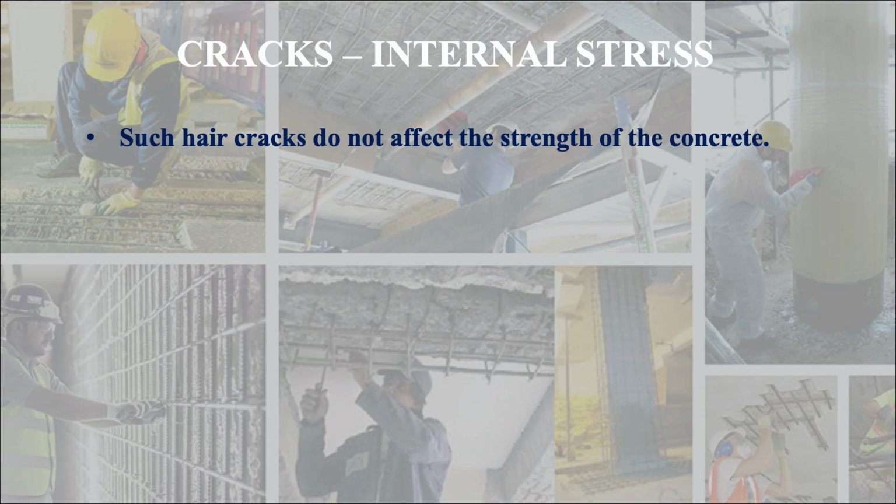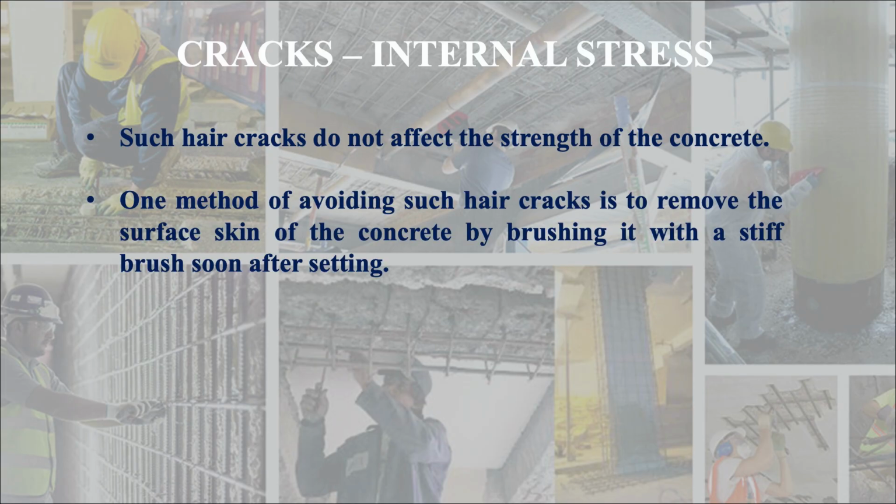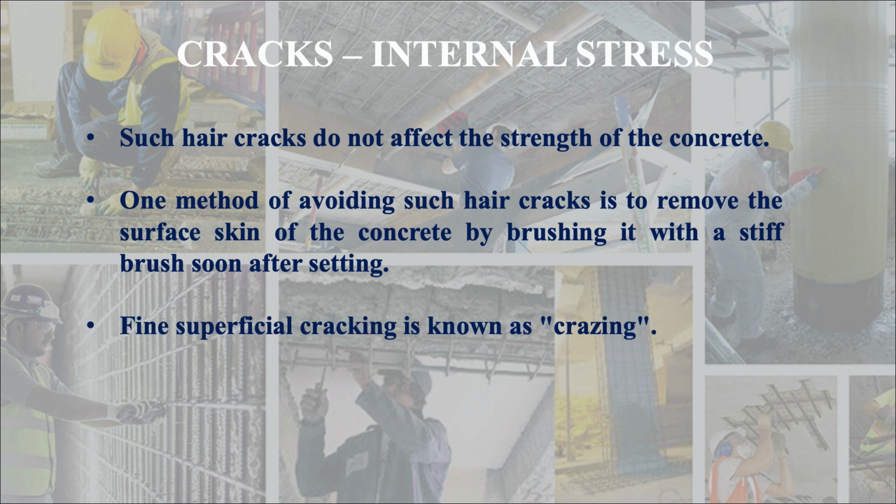Such hair cracks do not affect the strength of concrete. One method of avoiding such hair cracks is to remove the surface skin of the concrete by brushing it with a stiff brush soon after setting. Fine superficial cracking is known as crazing.